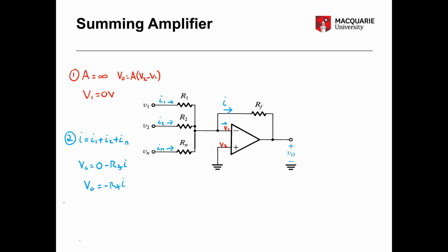Now before we proceed, we'll just note that through conventional notation of the op-amp inputs, we have two V1s. So we'll just label this one V1 minus for clarity. So when using superposition, to find out the current of interest, you simply ground the other inputs.